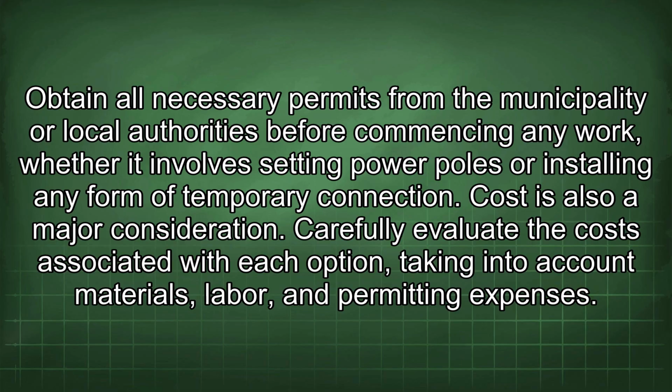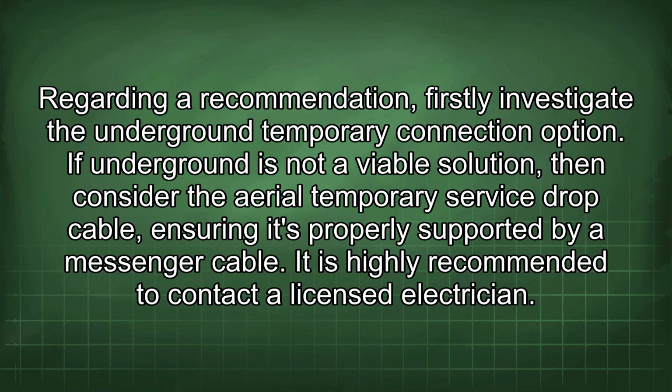Cost is also a major consideration. Carefully evaluate the costs associated with each option, taking into account materials, labor, and permitting expenses. Regarding a recommendation, firstly investigate the underground temporary connection option. If underground is not a viable solution, then consider the aerial temporary service drop cable, ensuring it's properly supported by a messenger cable. It is highly recommended to contact a licensed electrician.